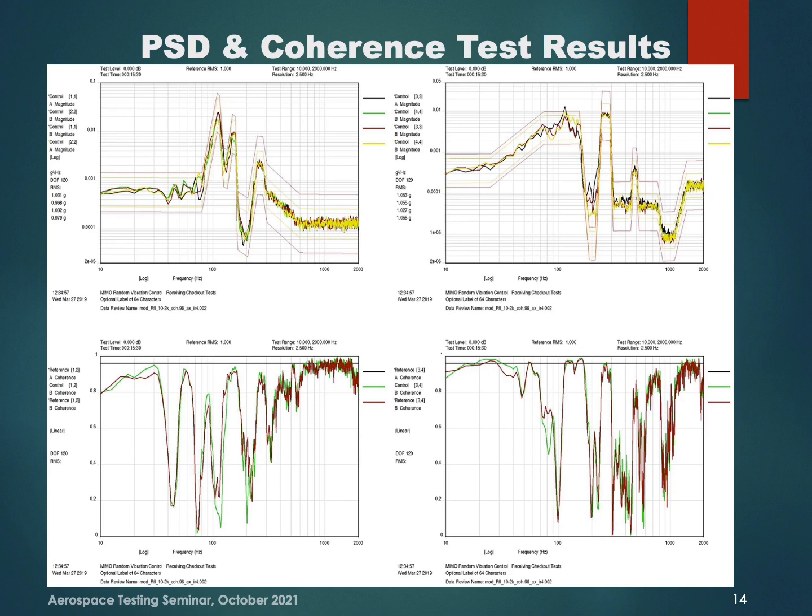So you can see that the coherence was lowered at various frequencies due to the nonlinear and facility limitations that were present in the test. The green trace is always close to the modified reference, and on the right we see the same sort of display for the coherence between the Z1 and Z2 accelerometers, again showing the same type of behavior.